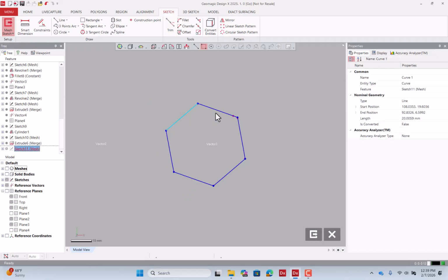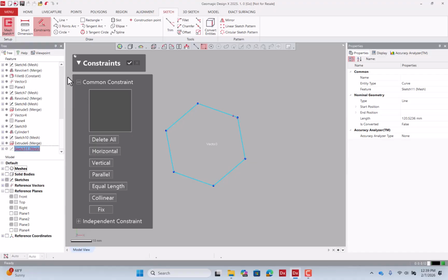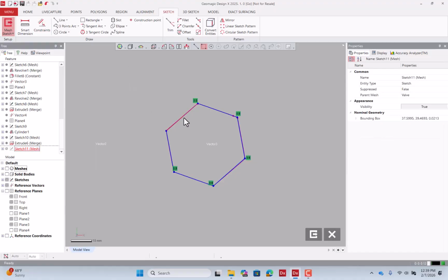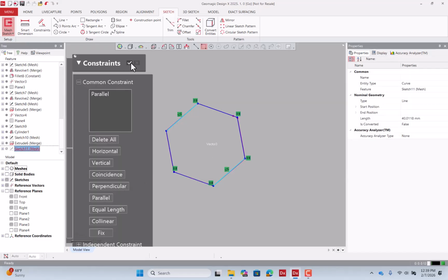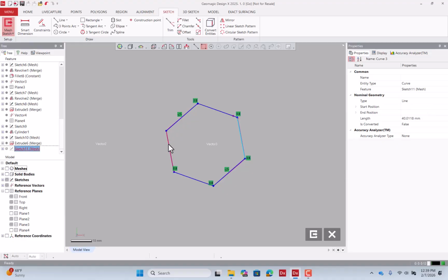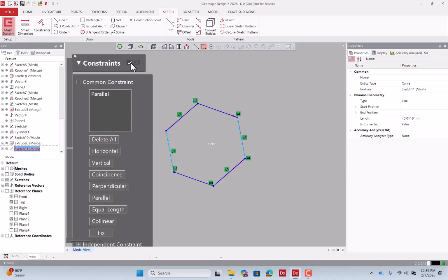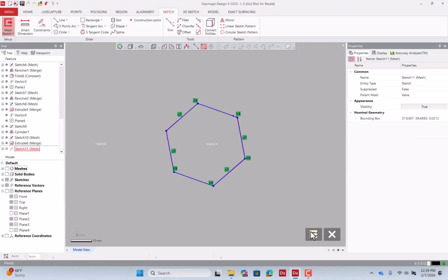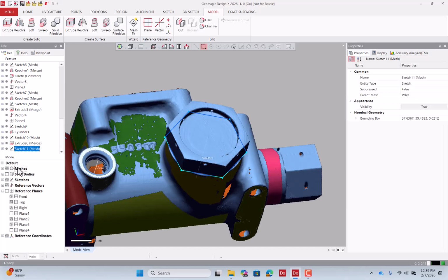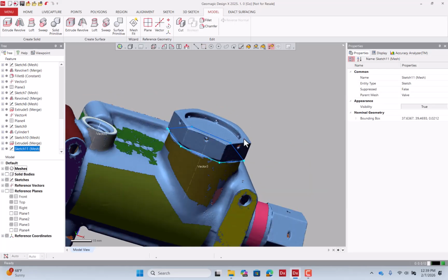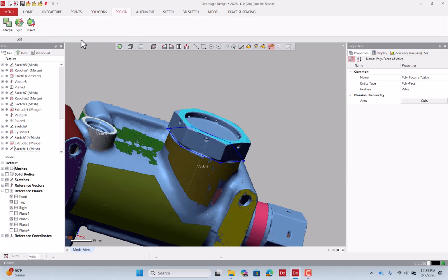And following that, we can choose these lines. I'm control clicking on these lines. I have all lines selected. I go to constraints and I can say make them all equal length. You can add further constraints like make these two lines parallel. Any sort of these constraints can be added as needed to make your particular bolt.